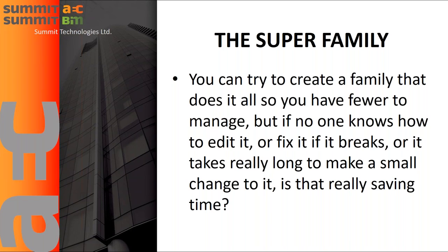And a lot of times if they can't figure that out, they're going to try cheating and doing lines for the family or some other way. So it's a balance between making it complex so that you have fewer families, but also making sure that it's not so complex that the amount of time you spend editing that family equals the amount of time that you would have spent editing 2 or 3 more families.